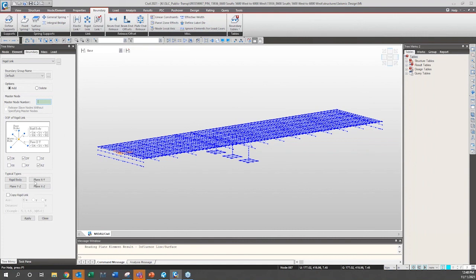In that case, I think what we ended up doing was realizing that the rigid diaphragm deck was going to control the movement more than the steel arch itself would, just due to its rigidity. You weren't going to bully that deck into doing anything it didn't want to do. The steel arch wasn't going to be able to force that deck to do something it didn't want to do, because it was stiffer. It was just not going to move. So it just depends on your scenario, once again.